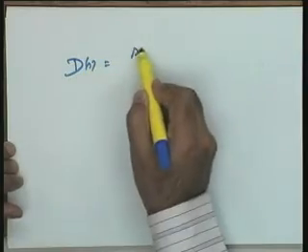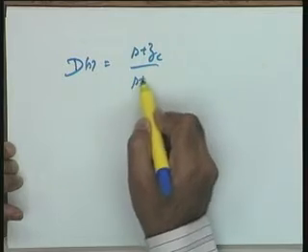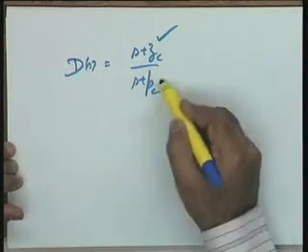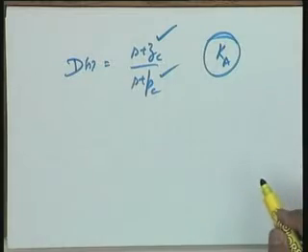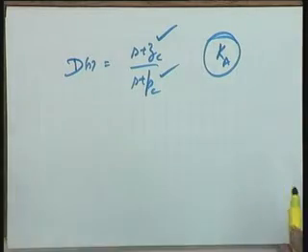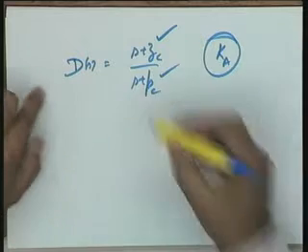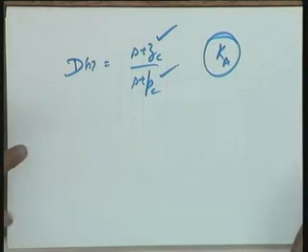So it means you can say that Ds is equal to S plus ZC over S plus PC. So ZC and PC are the two parameters and the amplifier gain Ka. These are the three total parameters available for design. And with these three parameters, using this type of network, you will find that it is possible to get the steady state and the transient requirements met.